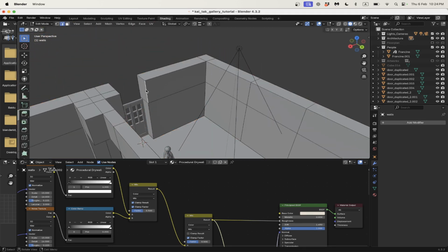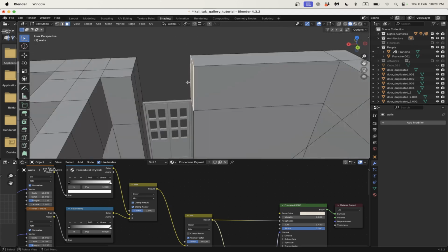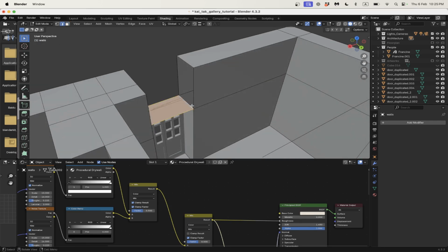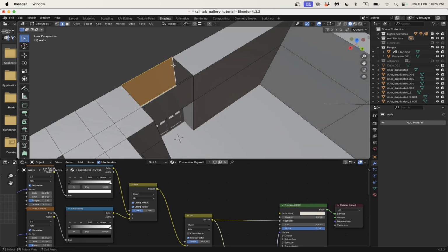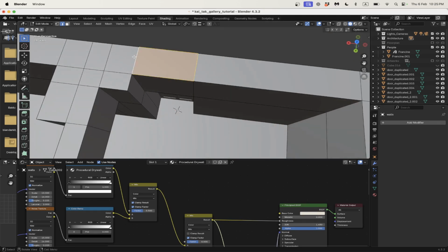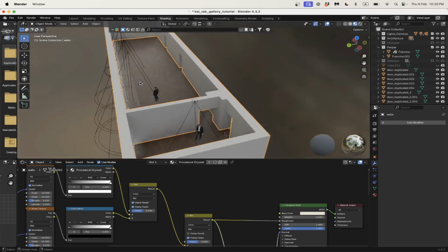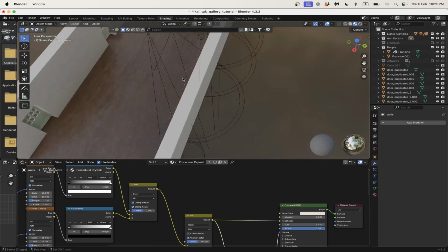Remember, if your viewport is sort of not zooming in the way you want it, just click on something where you want to be looking and go View, Frame Selected, and then Face Select, and just go back to work. Okay, delete my faces, and I'll just fill. Now if I press Z and go back into Material Preview, okay, we're starting to look even closer.